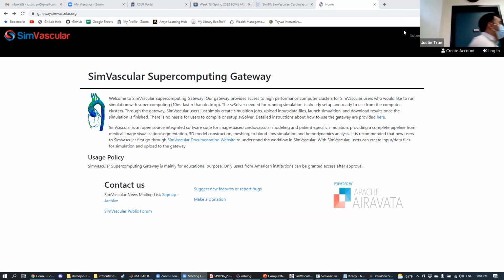I was going to ask if you have any advice besides running the mesh. Typically what happens is that if your estimated mesh size is so small, it's detecting a very small feature. Remember we talked about the fine balance: whenever you have really small features, the mesh gets really small. This is the manifestation of it. Sometimes if you smooth, you can get rid of those small features, but sometimes you just have to remove them. I would try to do a scan on your model and see if there are any small features.